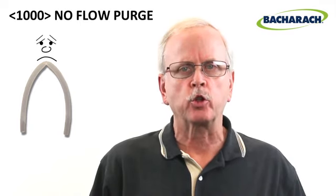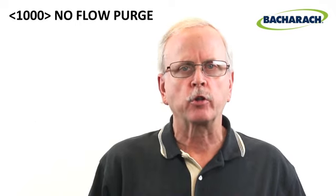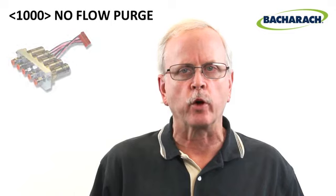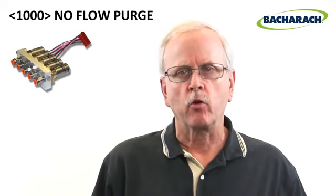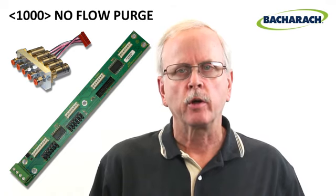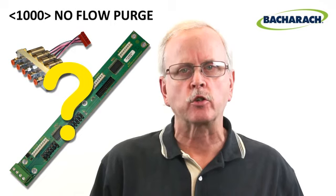If removing the purge tubing did not diagnose the problem, the no-flow purge fault is likely being caused by either a mechanical issue related to the solenoids in the manifold assembly or an electrical issue related to the printed circuit board that drives the solenoids. In each of these cases, you will need to continue your investigation to diagnose those components.